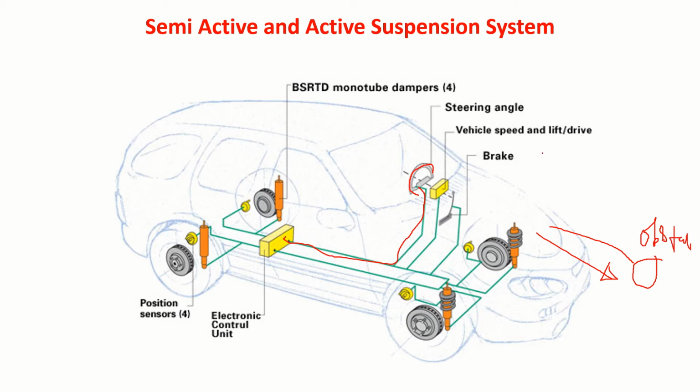Then whether you are braking or not, correct, whether you are accelerating. So all these kind of inputs are given so that the ECU, electronic control unit, as per the logic, can calculate what should be the damping and stiffness value.